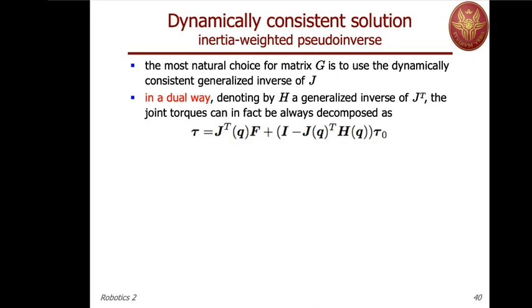In fact, remember that we have contact force, generalized contact force at the Cartesian level somewhere on the robot structure, and then we work in the joint space with torques. So the mapping is in general tau equal J transpose F. Now the J is in fact the J of the original task, so for instance an end-effector motion, so it's something that we know, and F is some force that will be a control force.